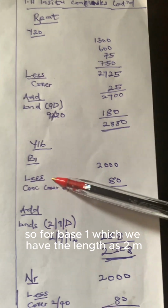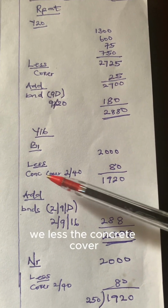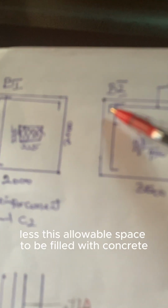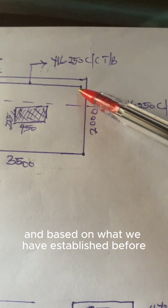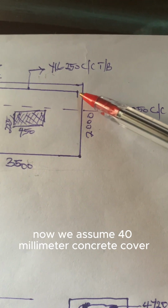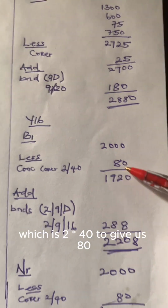So for base 1, which has a length of 2 meters, that's 2000 millimeter, we deduct the concrete cover. In this case, we deduct the allowable space to be filled with concrete. You can see that there is a tiny space here, and based on what we have established before now, we assume 40 millimeter concrete cover in the foundation.